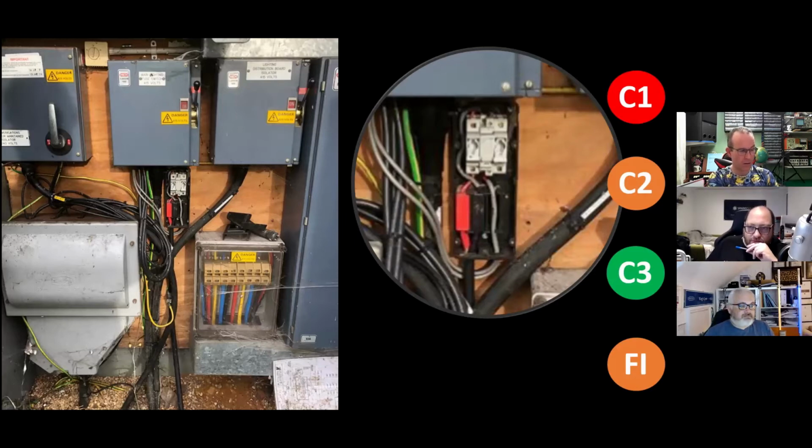Would an electrician? No, because they're not familiar with the equipment. Right, exactly. So in this situation, if this is in a cupboard, we would just close it and try to keep that secure. If it was readily accessible, what would you do? I'd put a barrier between it. I'd find somewhere to put a barrier. That's part of the CPD. Barriers, signage, communication with the client, and immediate contact with the DNO. Yeah, all that. Absolutely.